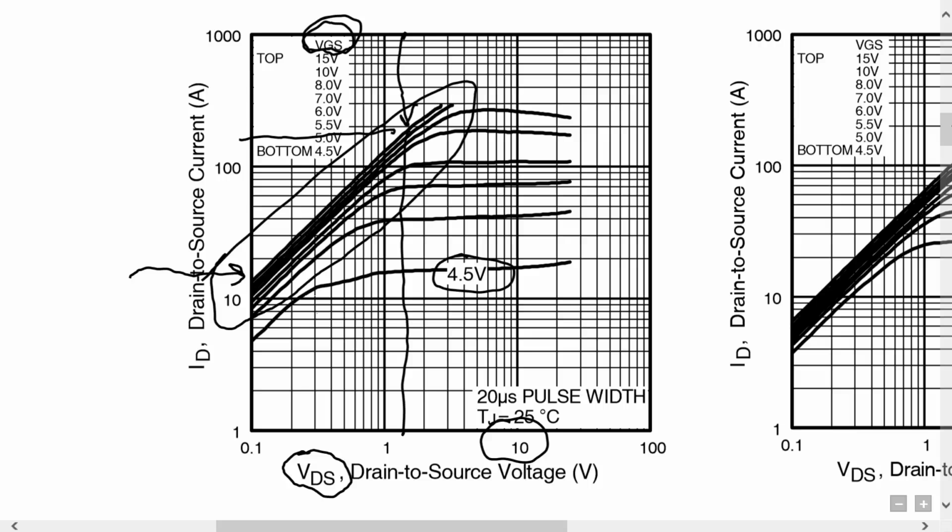And so what they're saying is the very top one, you have 15 volts. Threshold is 4. If you apply 15, you're going to be up here at the top end of that spectrum. So that's basically how then when you buy this thing, you know what kind of voltages you have available to you, because normally you don't want to burn up your power in the switch. You'd be looking to see if you can get the voltage that you need to drive this particular FET. So that's what this diagram here is for.